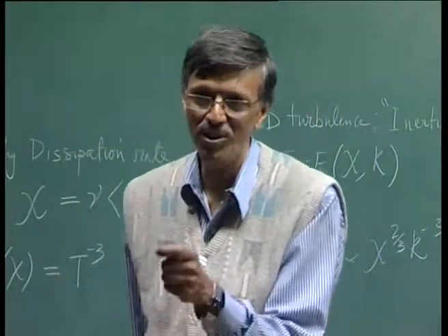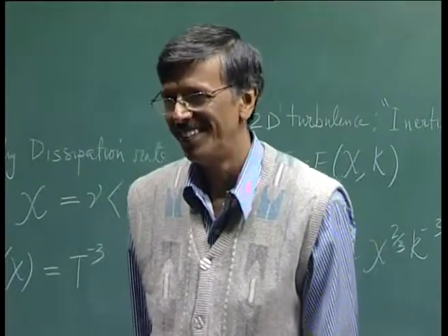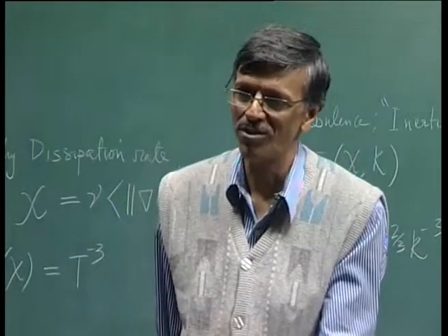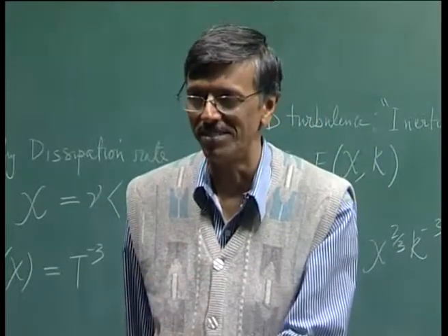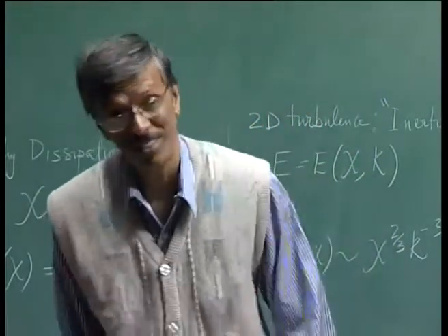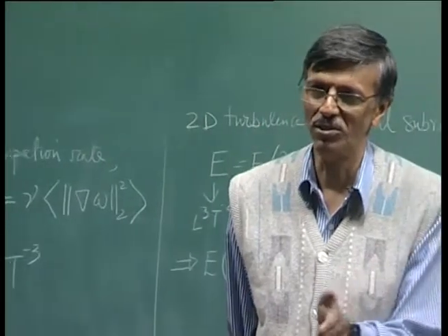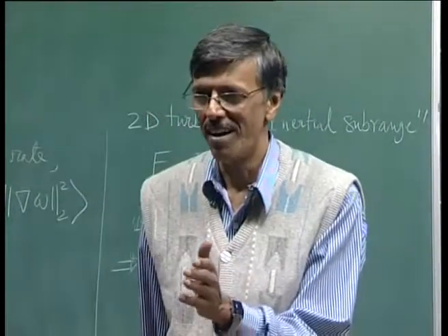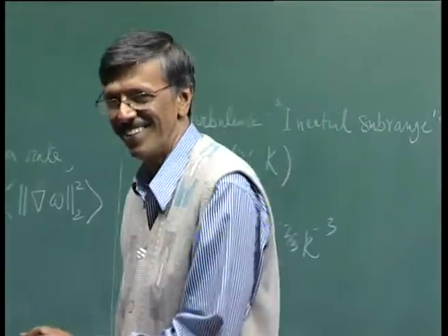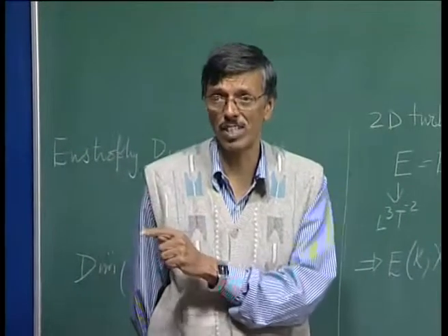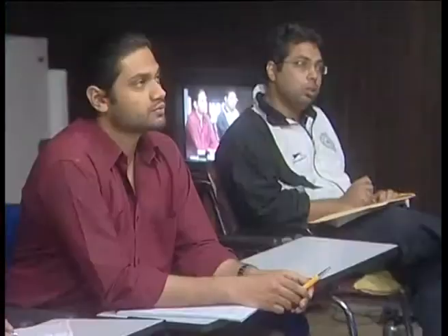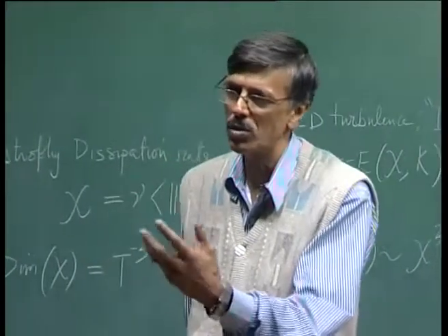So, you see, this is also something we touched upon when we talked about the Klebanoff mode. Why could Taylor not detect the TS wave? Because he was using a mechanical vibration, like the vibrating ribbon, but his frequency did not match. So, it is very, very important, if you are trying to compare your theoretical result with experimental result, you must compare apples with apples, not apples with oranges, right. But if you do have acoustic excitation, like we did some calculations a few years ago for supersonic flow, you can create disturbance waves, but it may not work out like a TS wave. There we saw it is more like a bypass event.